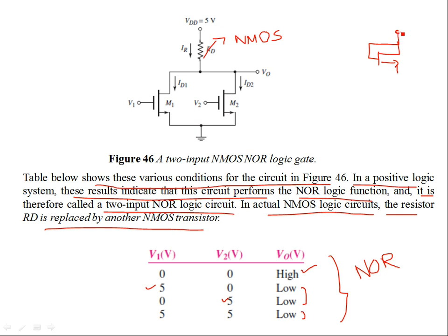The drain is clamped to VDD. This is a nonlinear resistor. I mean, instead of RD, you can have this configuration. No resistor, no physical resistor. This is also a MOSFET. This is an enhancement load device, which has a nonlinear IV characteristic, growing above threshold, something like this.